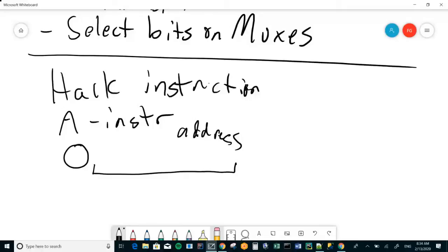With the A instruction then, this tells us both make sure you load the A register, and at the same time it tells that multiplexer make sure the thing going into the A register is the other bits from the instruction. Conversely, and we'll be talking about this in a moment, when we're thinking about resetting the A register based on an ALU output,